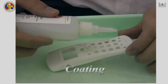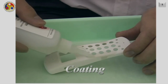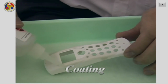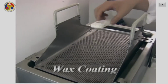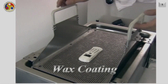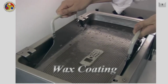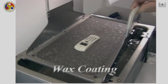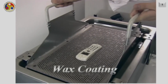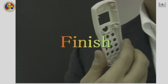After removal of this support material, the post processing can be done. Like here, a coating is provided to give strength to the part. Then the whole part is kept in molten wax and a uniform coating of wax is provided around the part. That will bind the particles from outside as well and will give it further strength. So, this is the final finished part which is wax coated.